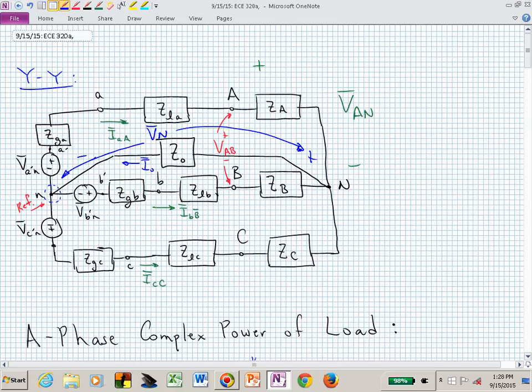Now what we don't know yet is, do we have current flowing through that neutral conductor? That's what we're trying to express in terms of some variables. Is it clear what I sub 0 is equal to in terms of these newly defined quantities? It's capital V sub N, which, if you had a voltmeter, you would put the positive lead at capital N and the negative lead at little n.